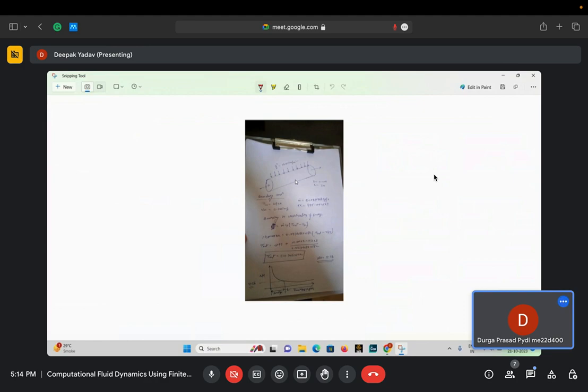Sir, I can, or maybe we will take it at the end of the session. So basically your problem is that the mesh is converged, but you do not know how to exactly get the Nusselt number from the data. Yes. For fully developed flow, the value of Nusselt number equals 4.36, on the wall, for constant heat flux. I want to validate this result.